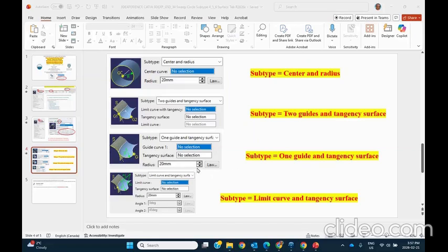And we want to draw a surface that starts at the guide, includes the guide, and then it becomes tangent to the given surface. And it's made of circles of specified radius. Remember, we are dealing with a profile type, which is a circle. So the surfaces that we're generating are all made by a whole whack of surfaces attaching generated circles together.